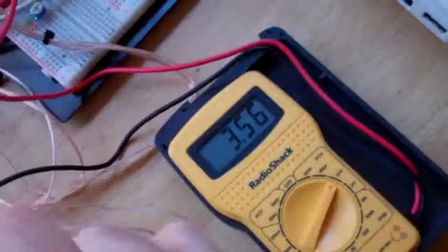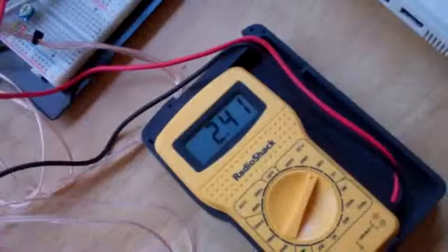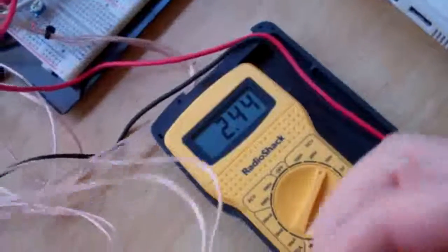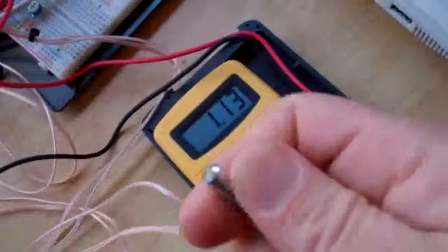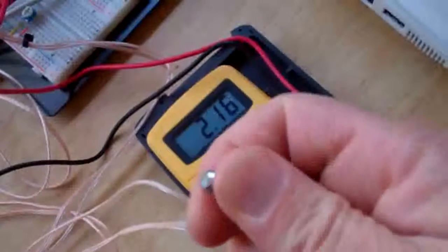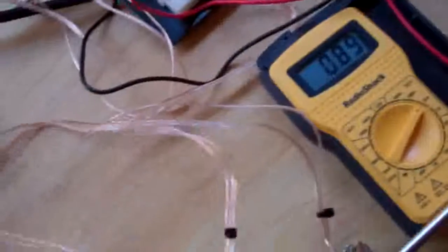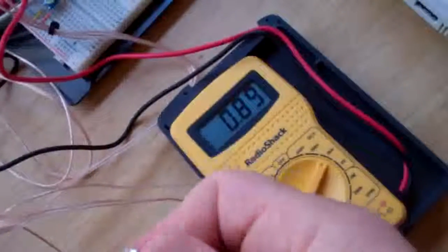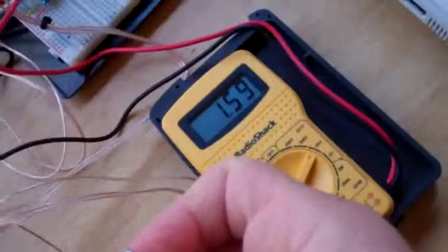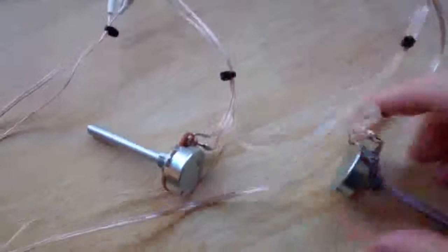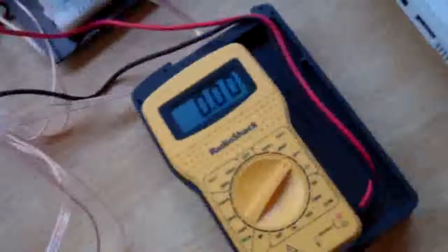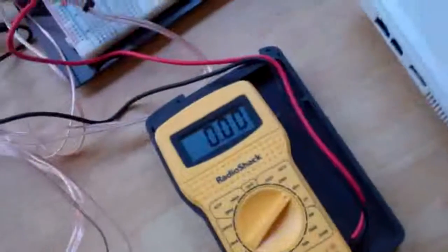And we can take the first potentiometer and divide that down. So now we're going from 0 up to 2.4, and the second potentiometer will run from 0 up to 2.4. Or we can cut that down and scale with the first up to approximately twice that value, or back down to 0. So we have a simple multiplication function, takes in two analog values between 0 and 5 and produces an analog value between 0 and 5.